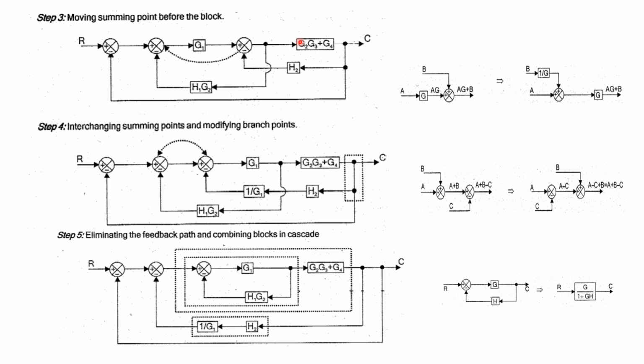That is this G2, G3, G4 plus G4 and H2. This is a negative feedback. This is overlapped with G1, H1, G2. This is also a negative feedback. Both are overlapped, so we have to separate this. For that, either we can move this branch point from here to here.